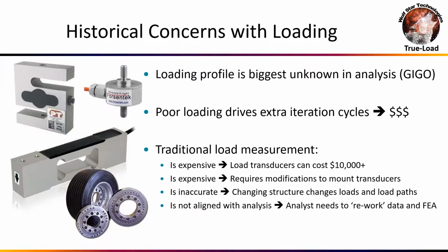So the way that we get around this is oftentimes people use load transducers, and load transducers are fine, but the issue with load transducers is that they're expensive, and they can cost upwards of $10,000. And every time you want to use them, you've got to modify your structure, cut away material, insert the load transducer, and now you're measuring something. It may or may not be the actual loads, and